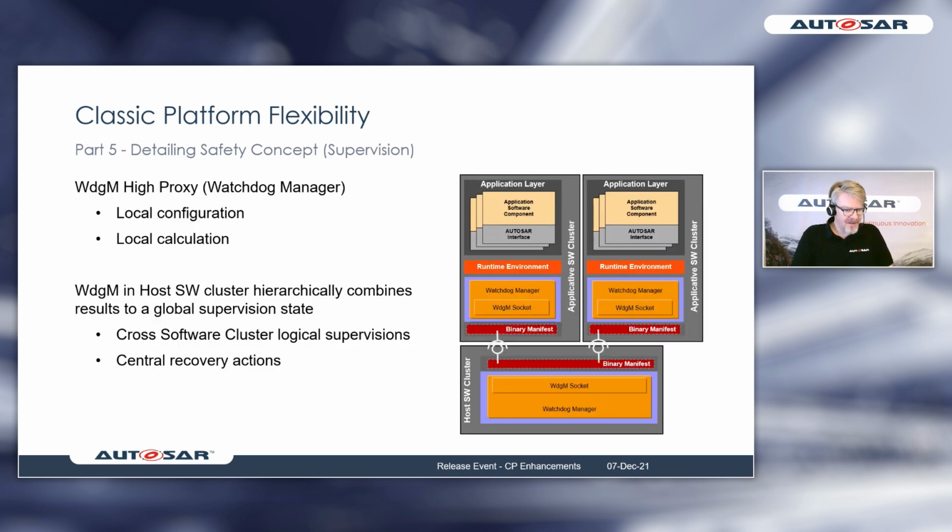Next for the safety concept is always the supervision, so the watchdog handling. You have from the safety work package also extensions to the watchdog manager, but here the focus is how to use the watchdog manager and all these supervisions in such a software cluster. Therefore, such a high proxy module was also added here with a local configuration, so that each software cluster can have an independent configuration and also a local calculation of these results. This local calculation is combined in hierarchical order in the host software cluster, so it is forwarded to the host software cluster where it can be combined.